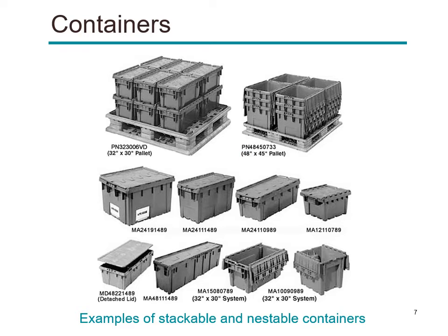There may be different standards, and depending on the size of the pallets, the sizes of the containers should be arranged. So there may be different sizes and dimensions for these containers depending on the dimensions of the parts that you are producing, and your decision on the size of the unit load. You should decide on the size of the container, and when you are deciding on the size of the container, you should consider the equipment, the pallets or skids that will carry these containers. The dimensions of those pallets and skids should also be considered.